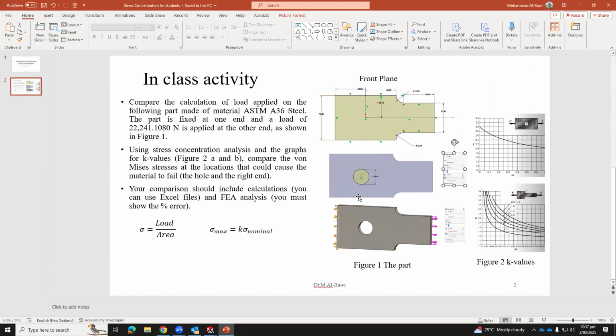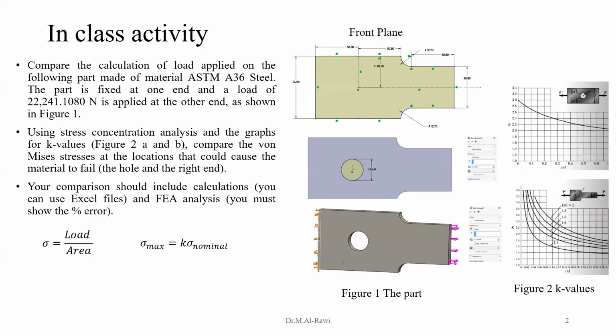And then you need to create that circle. That circle you just extrude through, as shown here, but with that diameter, so you can get it through to create that. So if I ask you from mechanical engineering perspective, strength of materials, where are the weakest points for this part shown in figure 1? Where do you think that any break or any failure of materials will be happening? The shaft, like we had the corners there. So that's corners here. No, and the circle as well. Circle is number 1. It's the top one.